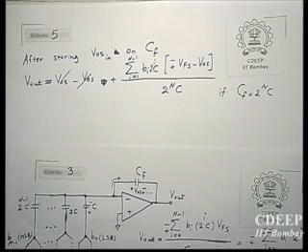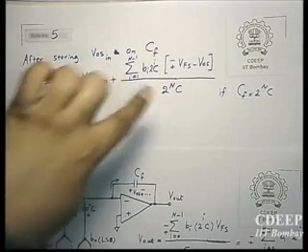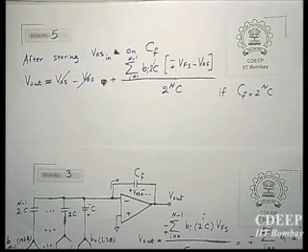What I mean is that if this offset is constant, it doesn't change with temperature or input, everything is constant, this offset voltage across the entire conversion cycle, then you can do it only once and then the DAC can operate, or you can do it once in a while.